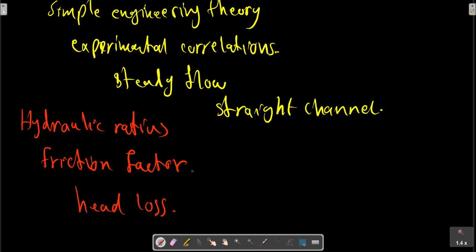Simply stated, open channel flow is the flow of a liquid in contact with a free surface. As we said before, there are many practical examples: both artificial flows, spillways, canals, weirs, drainage ditches and culverts, and natural streams, rivers, and flood plains. This chapter introduces the elementary analysis of such flows, which are dominated by the effect of gravity. The presence of the free surface, which is essentially at atmospheric pressure, both helps and hurts the analysis.